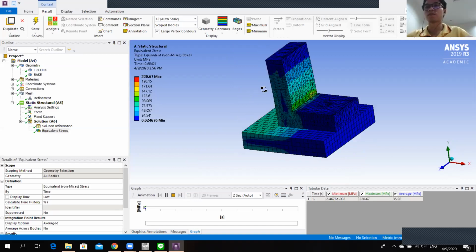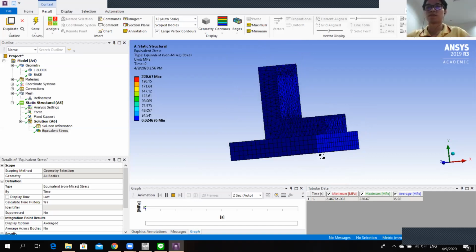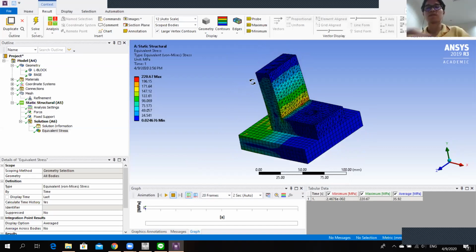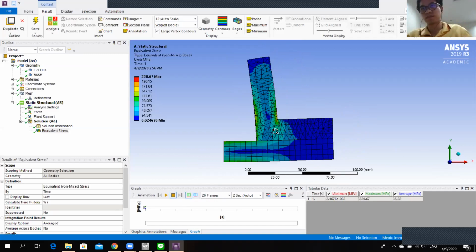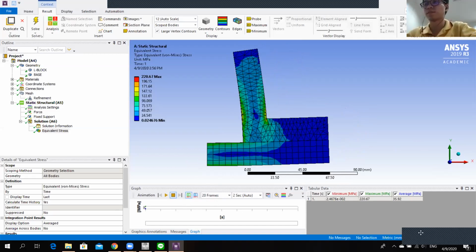Okay, now I would like to comment again, just to connect to what I said before. If you look at what you showed us just 1 second before, the side view, you can see how the lower part of the aluminium part and the steel part are really acting as one stiff body. This is what I meant. Basically, we are creating a sandwich that is not really a sandwich, right? So we're not only adding the two bending stiffnesses, but through the stiff bond, it's basically becoming 8 times stiffer than before, assuming for a second this would be the same material, because of the basic formula of the bending moment of inertia, which has the height of the profile to the power of 3. So this is now acting as if it was 8 times stiffer than each of the two parts.